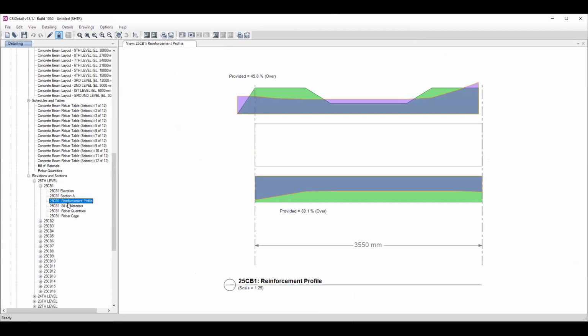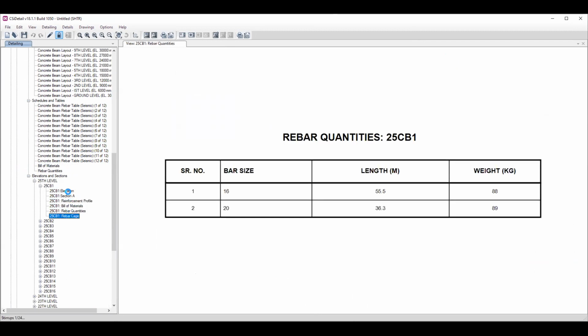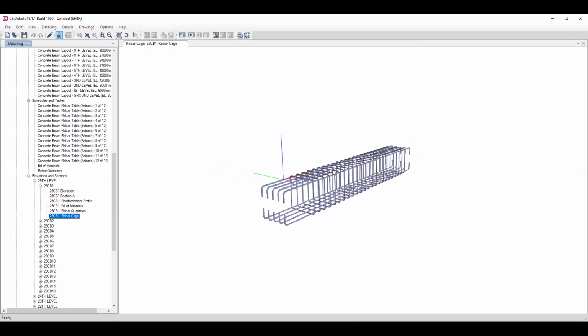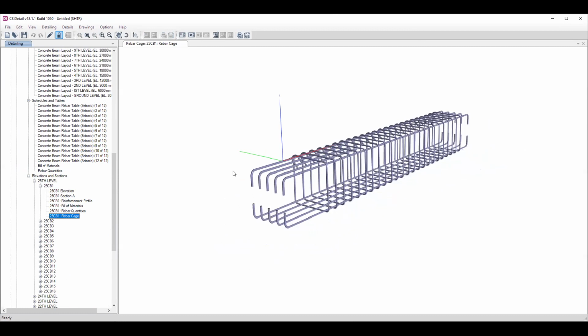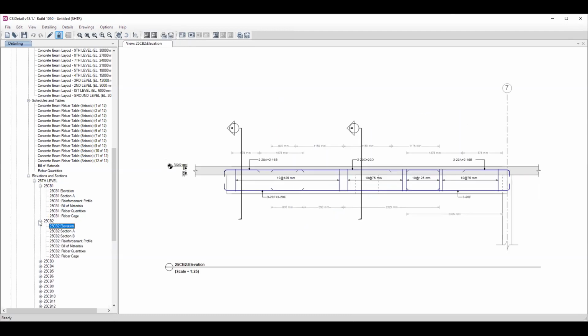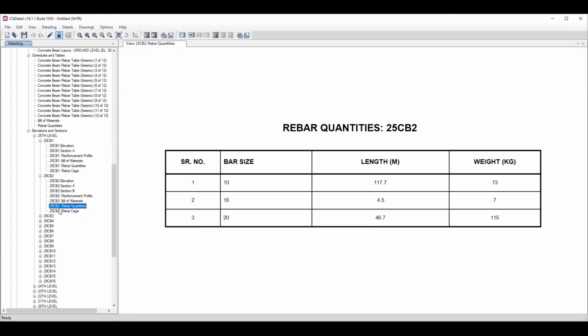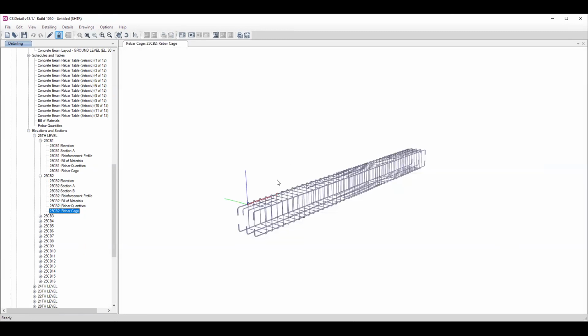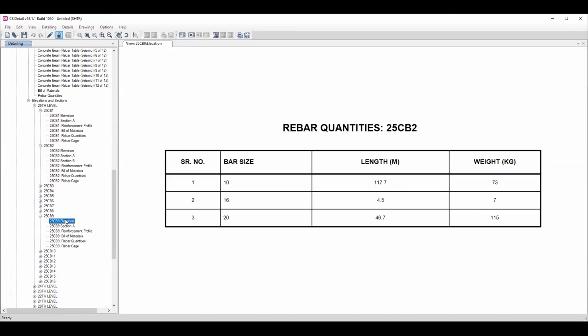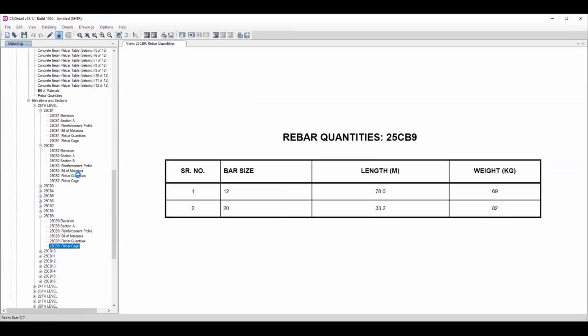Okay, hello, everyone, you are saying that we can utilize this file, like this is the 3D model, like how you have to reinforce this one. But see, this reinforcement, like at each beam and column, it may change. So you need to take precautions. Most of the people are providing same reinforcement in the whole structure. So that is a very wrong thing. You need to check all the things very carefully, like which bar you are using and where you need to, like here you are seeing there is some differences. After that, all of you get this point, like how you can reinforce and get the details.